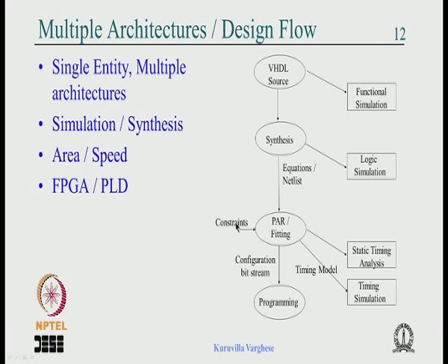So that is IO constraints, and we have seen the expression for minimum clock period in a register to register path. It is possible to specify timing constraints. You can say that when the algorithm does the place and route, I would like to have a register to register path with a delay of 5 nanoseconds, because we are planning to clock the circuit at 200 megahertz.